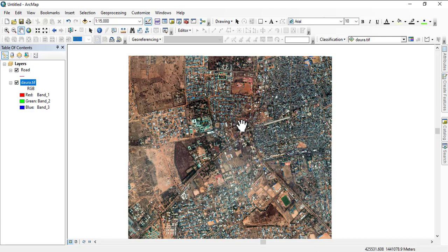Only in terms of footpaths, not all of them are necessarily connecting to a minor road or a major road or an expressway. So you need to start with the ones that cover the entire area. So we will digitize these first, before we sort out the major road and then the minor road. So that is basically what you do best.